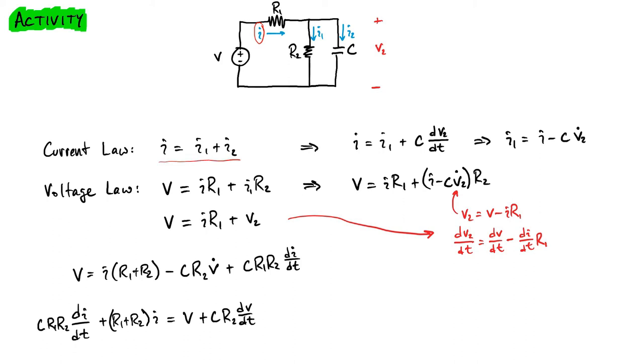In this case, it becomes useful to write down both versions of our Kirchhoff law because they end up not being completely redundant. So we'll write one voltage law that goes around this circle and another one that goes around this circle. And so this one describes the voltage across the source, across resistor 1, and then across resistor 2. And so that gives us this Kirchhoff's voltage law. The one that goes through the capacitor yields this relationship.